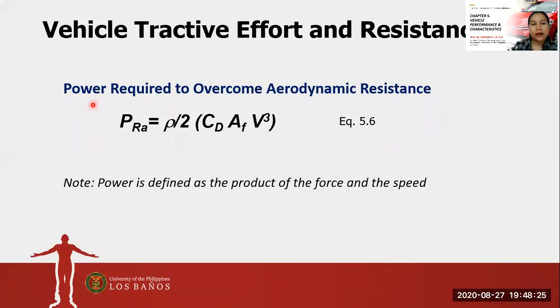Okay, now, what is the power required to overcome the aerodynamic resistance? The power is actually equal to RA itself multiplied by the speed. Note that power is defined as the product of the force and the speed.